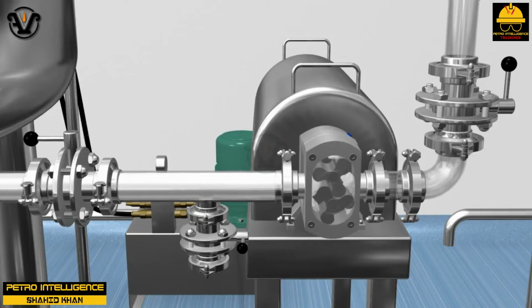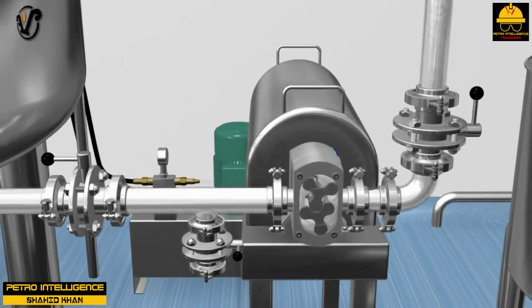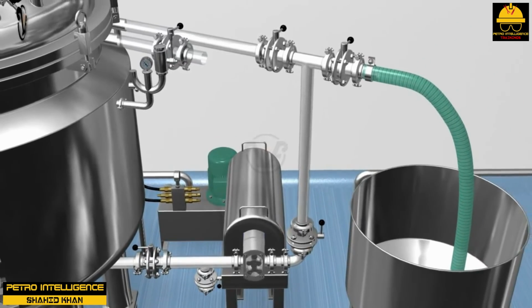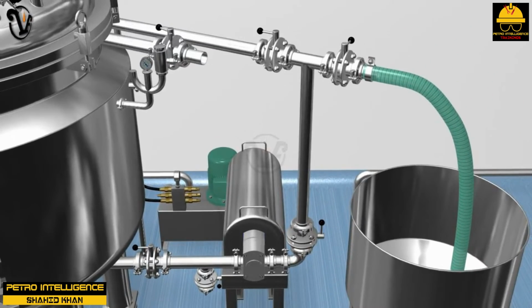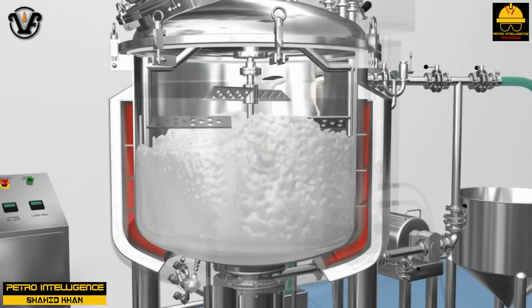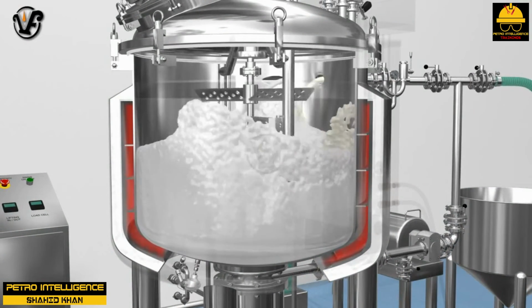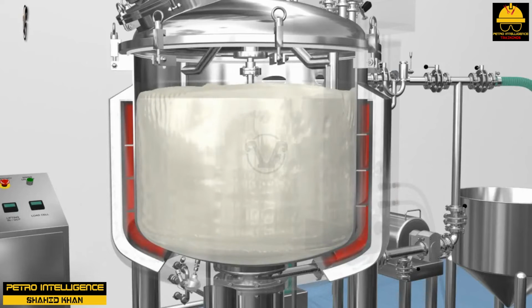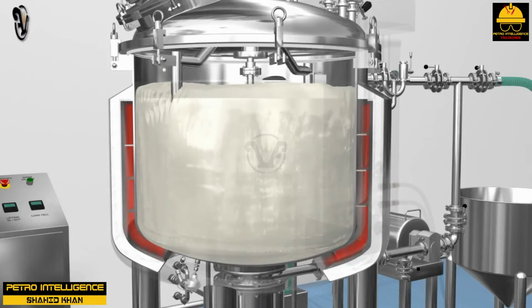Other considerations that must be taken into account are how much agitation is required to produce a uniform reaction mixture, what type of heat transfer equipment will be needed to prevent excessive fouling of the heat transfer surface, the minimum size of reactor that is needed to obtain the necessary reaction time, and whether a catalyst is needed to promote the reaction and how it will be added to prevent a localized reaction.